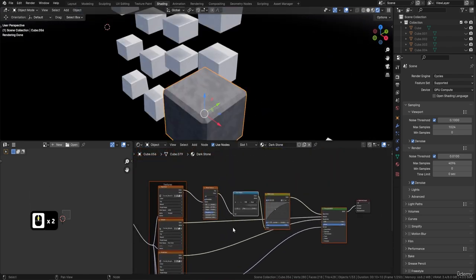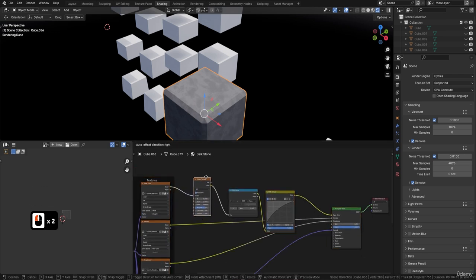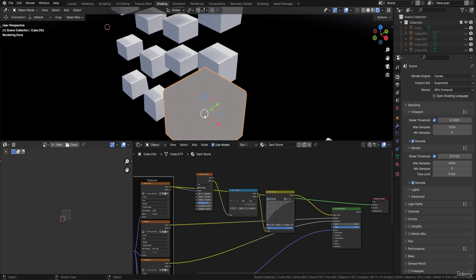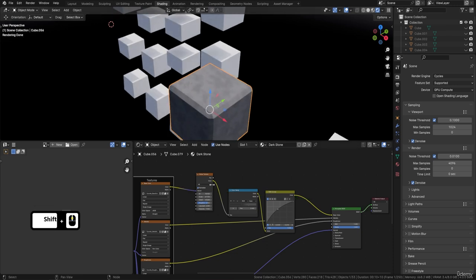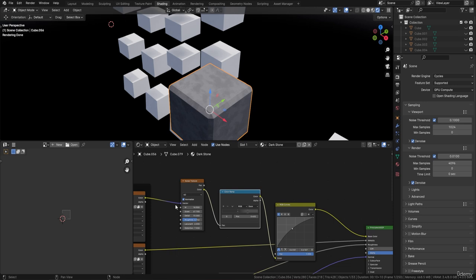Now we can see that, from the color, we've got a noise in there. If I plug just this in, you'll see this is the color it should be. So this is the color when it came in. But what I've done is I've brought some noise in. I brought in a noise texture and used a color ramp to distribute the noise around the texture we already had.